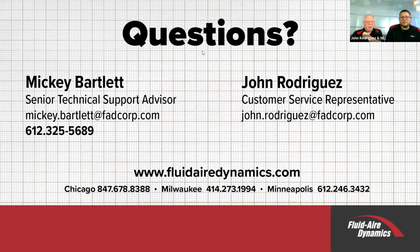But never run your piping system any higher than the needs of that largest PSI usage. For example, if one machine uses 100 PSI and that's the most, that's where you want your pressure to be. If you over pressurize your system, your leaks will leak more. And remember, your leaks aren't going to be in your piping for the most part, because they'll be fixed at the time you install. It's going to be on the drops, the quick disconnects, the hoses, the barb fittings. That's where you're going to find your leakage, and it may be a cylinder here or there. Again, variable speed machines just allow you to set your pressure by 1 pound at a time to have exactly the amount of pressure that you need downstream.